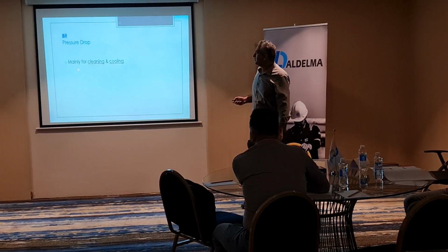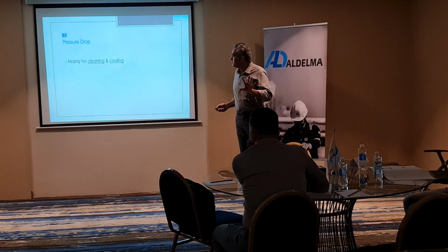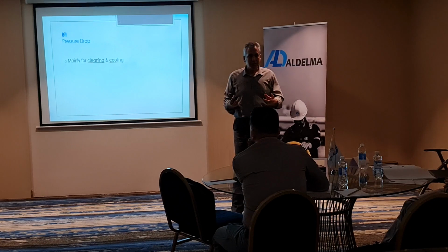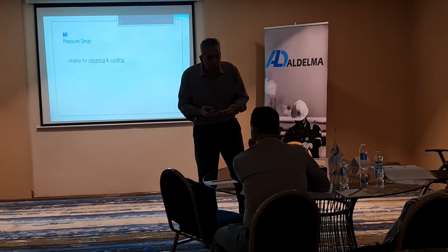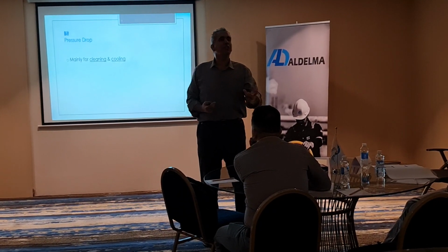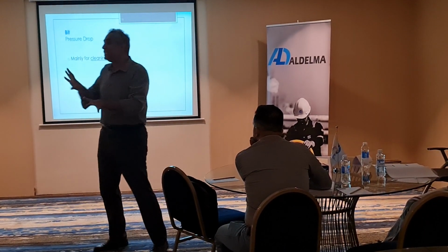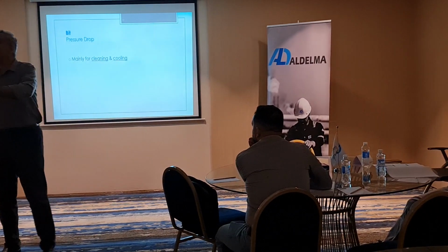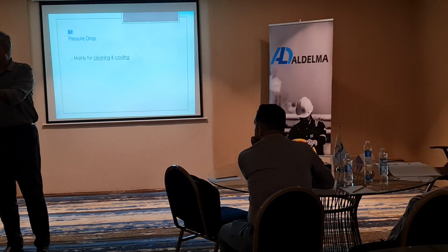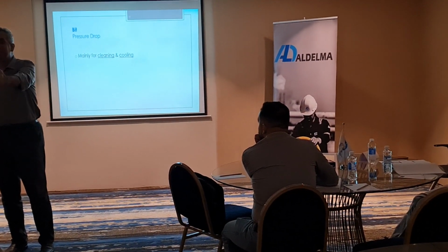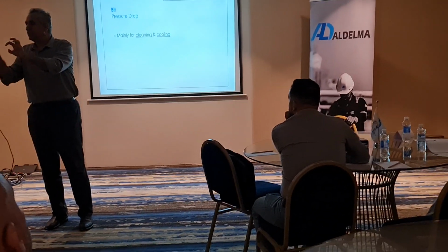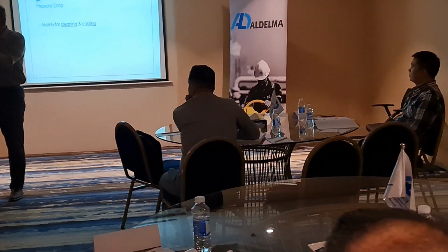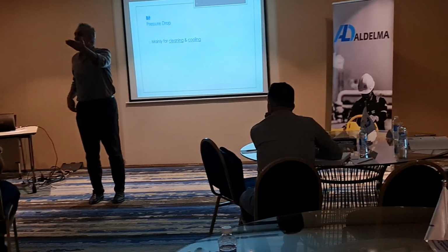Okay, this bit pressure drop is mainly for the cleaning and cooling. When we are not very deep, or it is not high pressure, high temperature, we have a jet nozzle. But when we go deeper and deeper, sometimes cleaning is not important. Cooling is important. That's why you have a water course, like in the diamond bit, impregnated bit. We eliminate the nozzle and create the water course. We'll discuss this part in the bit section tomorrow.